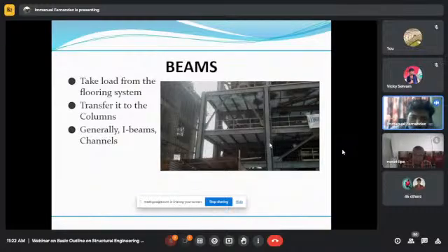And here we go with I sections, or see this is the column with star shape, because in steel you can create any shapes based on your requirement or based on your design to accommodate the structure. Since a single I section was not adequate, we have made a compounded section or a built-up section basically to take the loads of the structure. And in this structure we support all the equipments and platforms.